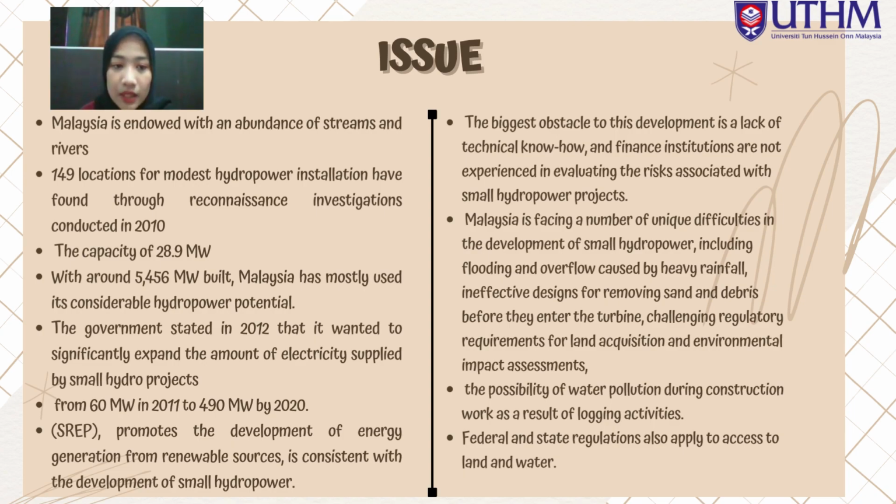In addition, Malaysia appears to be facing a number of unique difficulties in the development of small hydropower, including flooding and overflow caused by heavy rainfall, ineffective design for removing sand and debris before they enter the turbine, challenging regulatory requirements for land acquisition and environmental impact assessment, and the possibility of water pollution during construction work as a result of logging activities.